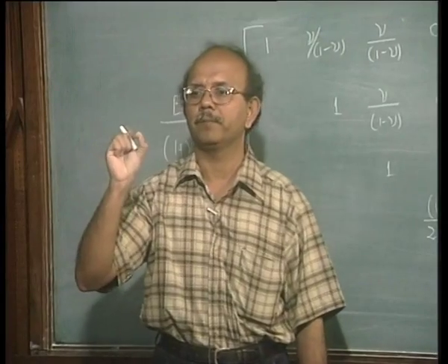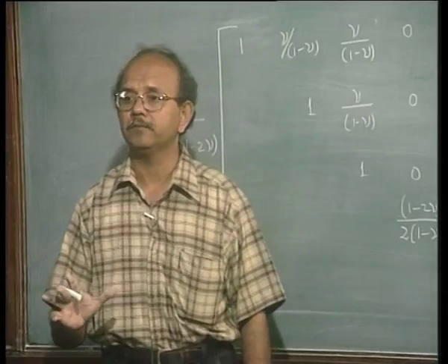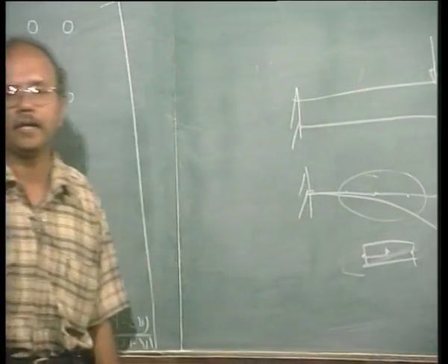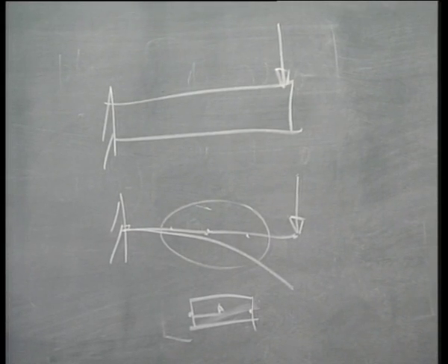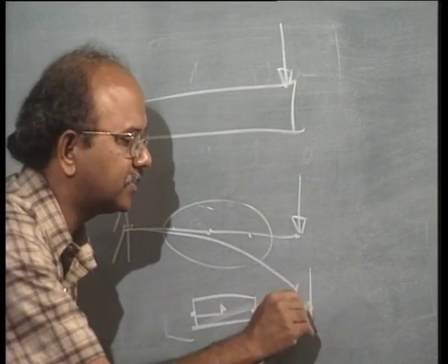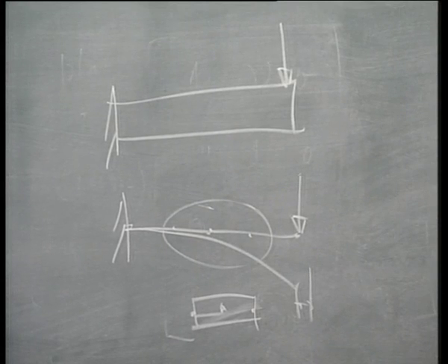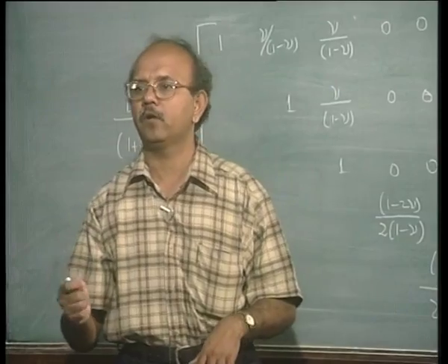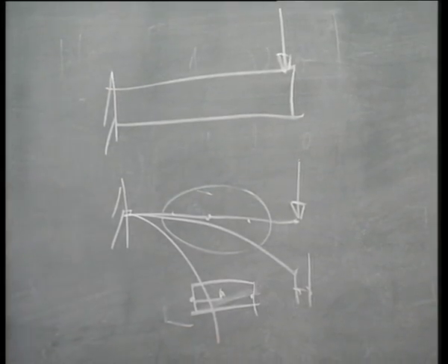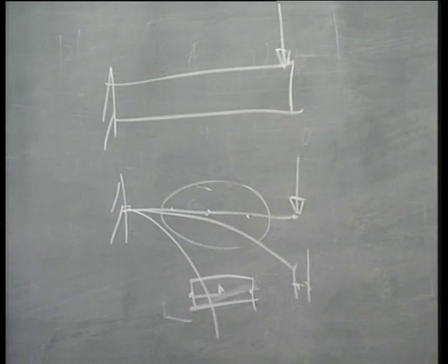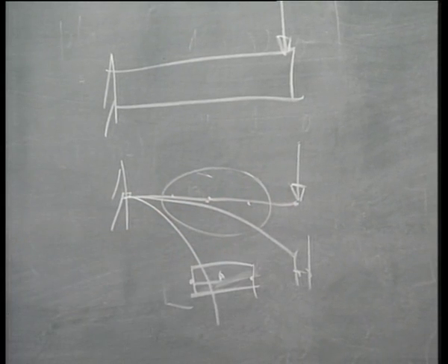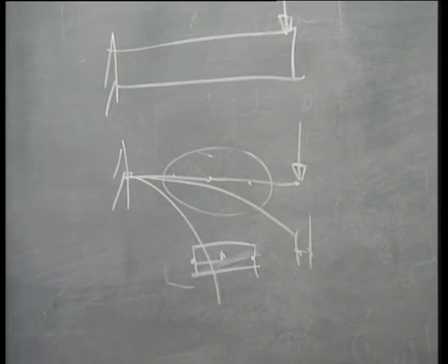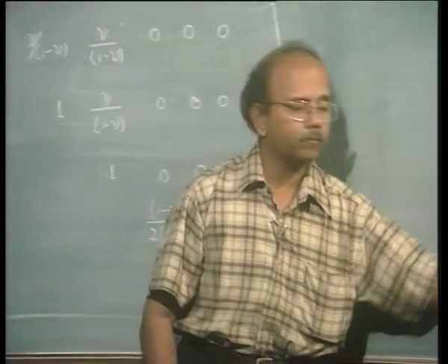We will first clarify the first one. We are now looking at only bending behavior, and what we are doing are all small displacement problems. So in other words, when there is a displacement like this under the application of the load that you see there, the effect of this movement here is extremely small. So this is a small displacement problem. Whereas suppose this beam is made up of rubber and you apply a lot of load, maybe this beam would take a shape something like that, it would just fall down, your load may fall down. We are not looking right now at this kind of problems, we are looking at small displacement and small strain problems. You already know what is large strain. Remember that the slope of displacement is far less than 1, that we had already seen. So you look at this thing.